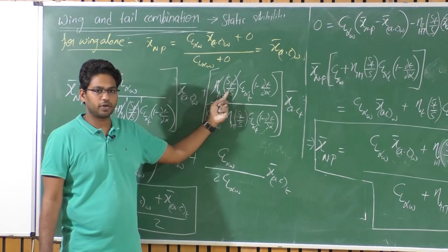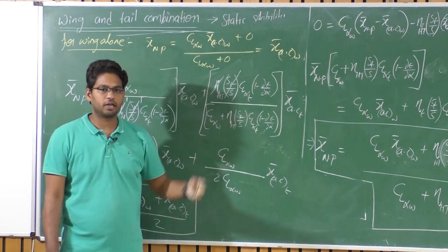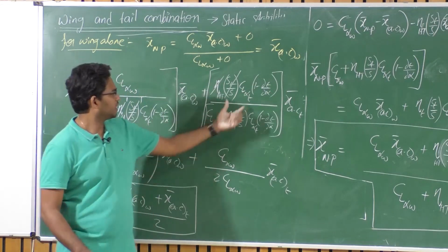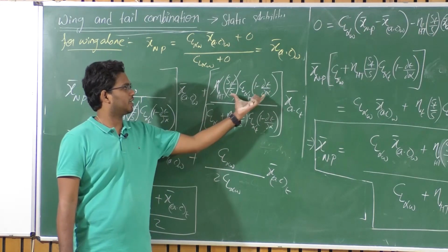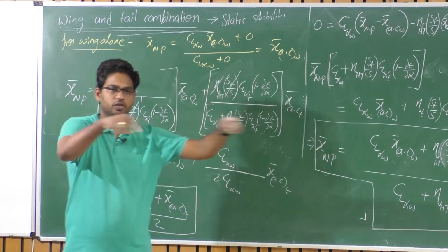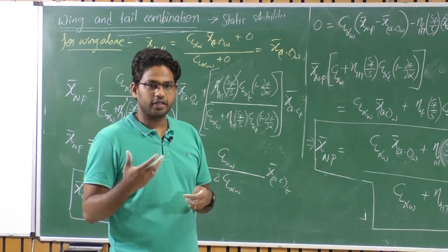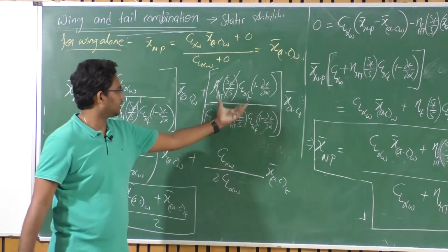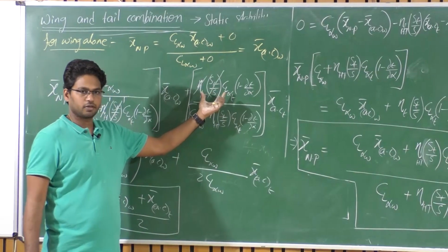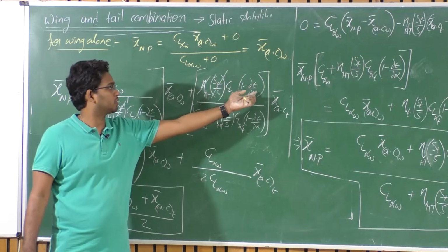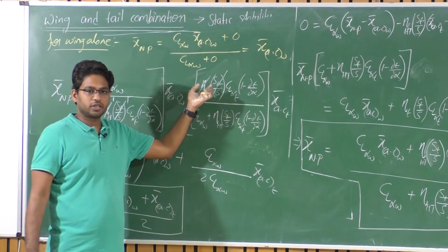This is just a normalizing factor. So this will be equal to the wing CL alpha itself. So this entire term is nothing but a correction factor to the CL alpha of that particular geometry. If it is just an identical wing, that is one and the same, if the downwash is 0 and this efficiency is 1.